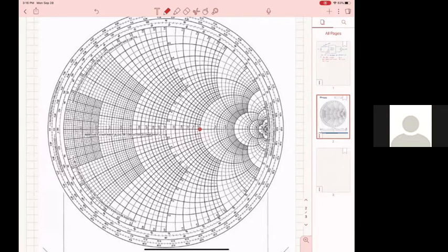A lot of times when you work in lower frequencies, you just put chips together, all right? You have like a semi-monolithic, so it's hybrid integration as we call it. So you take different chips, you put them together. So if your load is a different chip, then usually the way you connect them depends on the frequency. If you're at lower frequency, you can do just a bonding wire. So you go from the output of one to the input of the other.